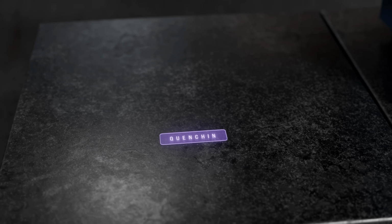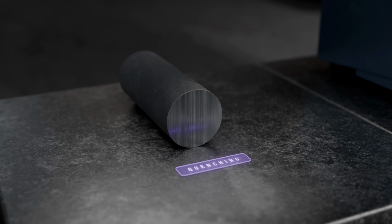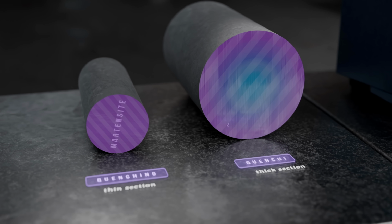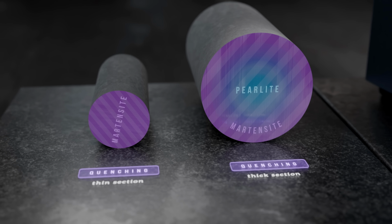The objective of quenching is to cool the material fast enough that austenite turns into martensite through the entire cross-section of the material. This can be challenging with thick components, where the core of the material will take longer to cool than the surface, resulting in pearlite or bainite forming within the part instead of martensite.